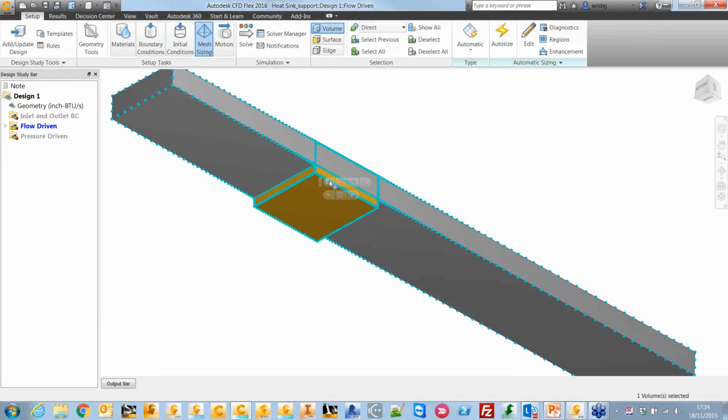It generally makes a little less sense than applying a heat load, especially if we... A surface heat flux might be a better example there, yep. Just that it's apples to apples instead of the temperature. Yeah, I agree. Here, either can work because it's underneath a solid. I guess the problem is if we've got a part in an air domain, when really we want to mesh the part. We want to assign a volumetric heat load so that we might enable radiation and it would work correctly.